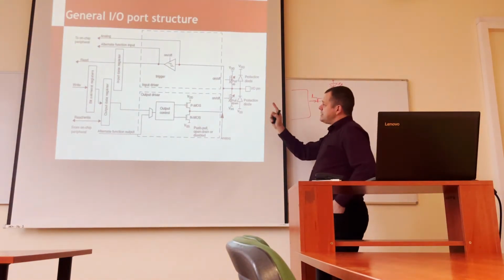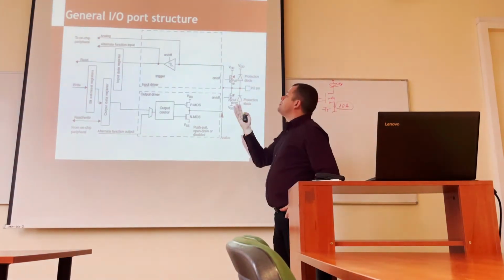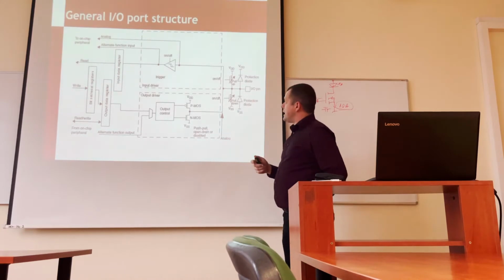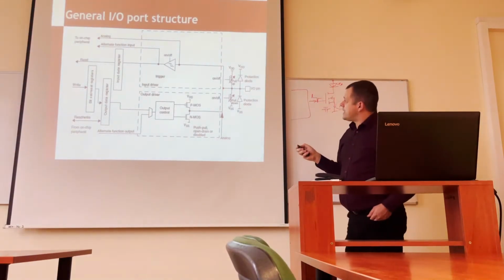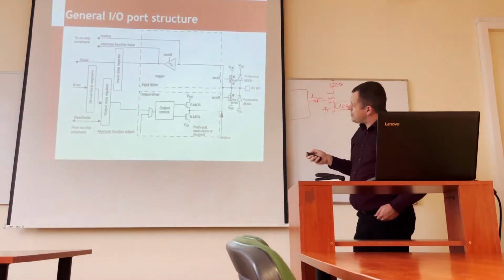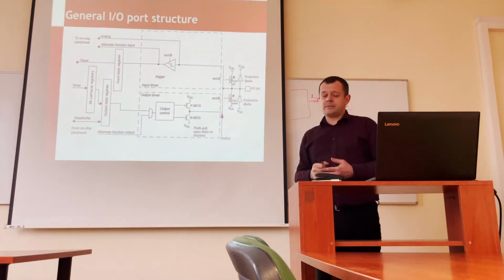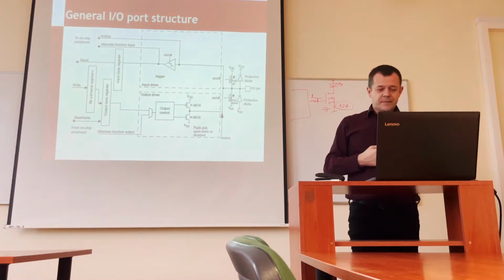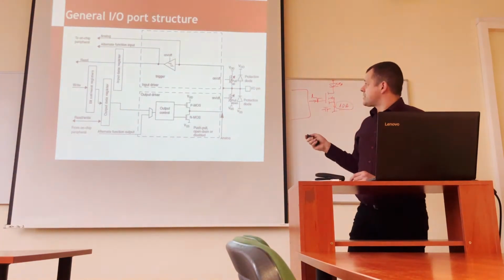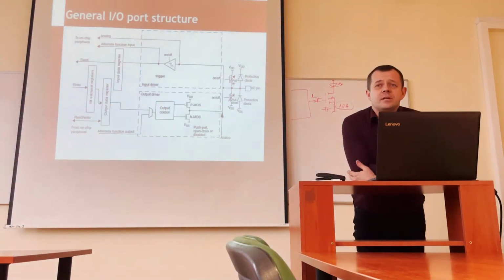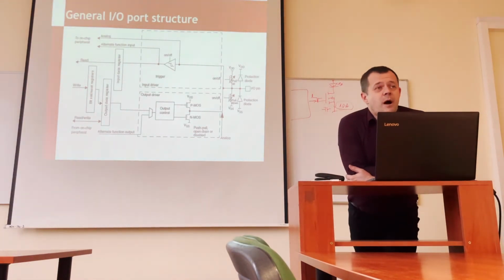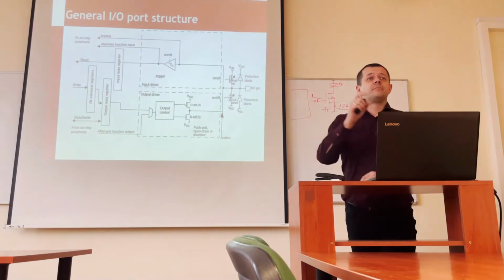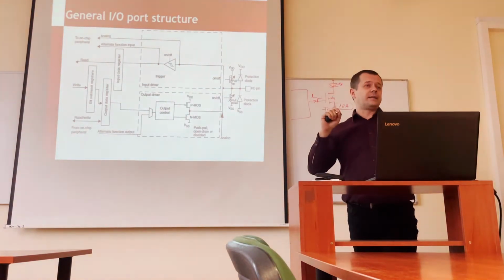Sometimes important roles are played by the pull-ups and pull-downs. Microcontrollers usually have pull-ups. It's much more rare to have pull-downs; it's really limited to some families which have them. Usually we just have pull-ups. Why do we need pull-ups? Of course, for wired OR. It is called the wired OR functionality, so that we combine many outputs on one line.